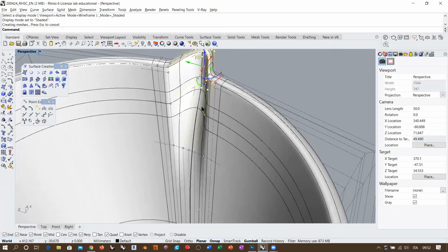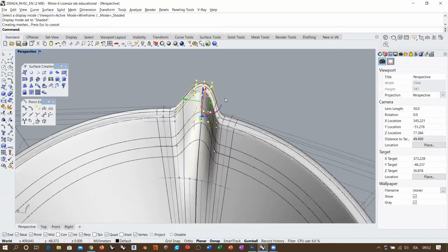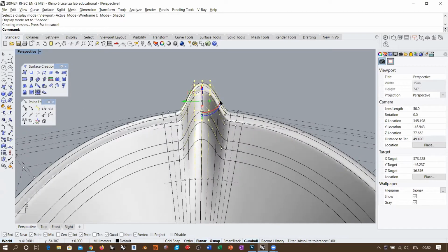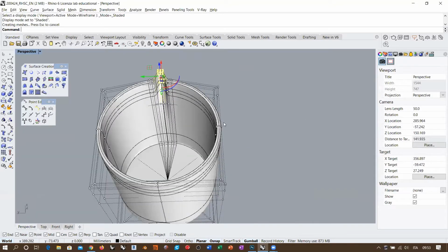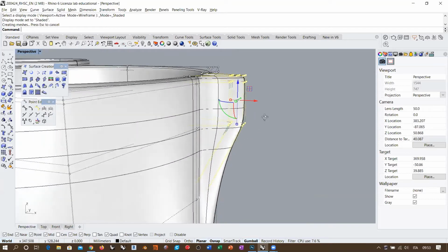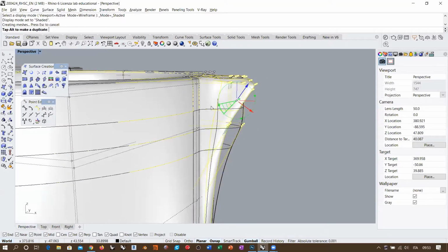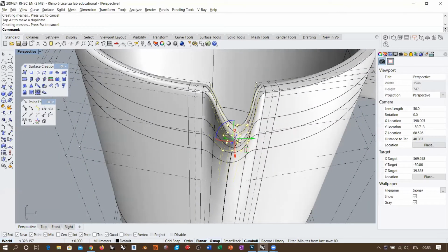Or well, yes, I'm working on kink points, but on the profile direction. Okay, which is smooth. And it's not producing any kink in the horizontal direction because I have created this structure of control points here on the sides. Okay, and I'm not touching this face of the original cube, let's call it so, and this face of the original cube. So everything stays smooth in this case. And I can play with these points as I want, like also creating this, because I'm not changing anything that regards the kink aspect of this surface.